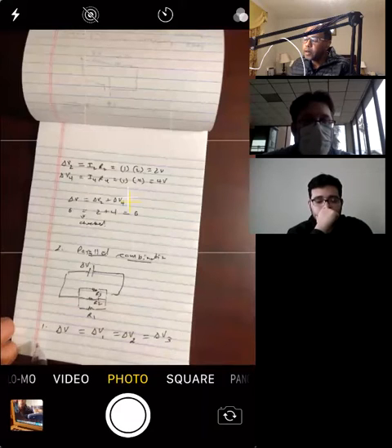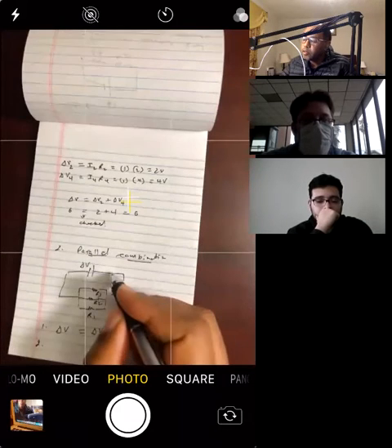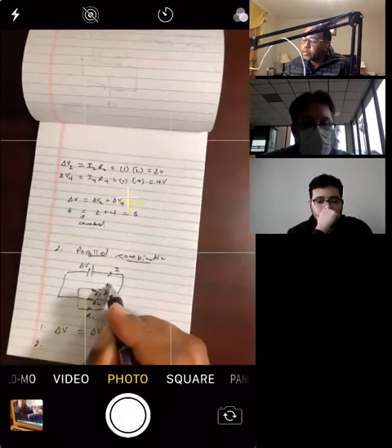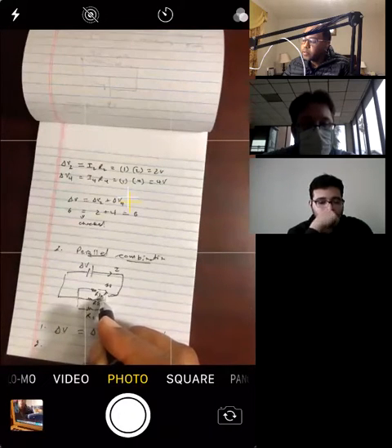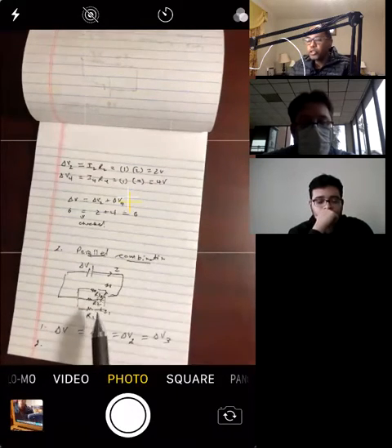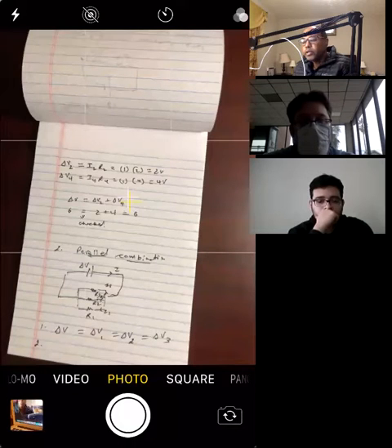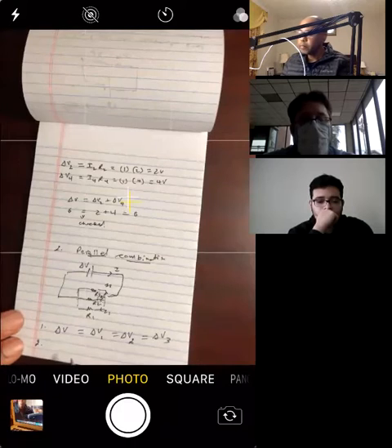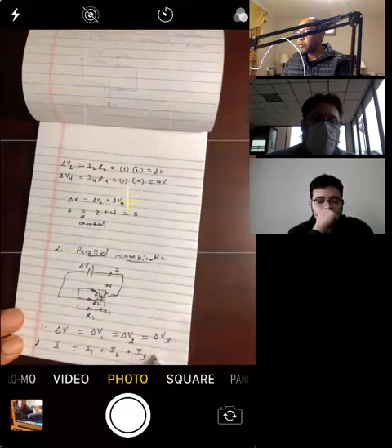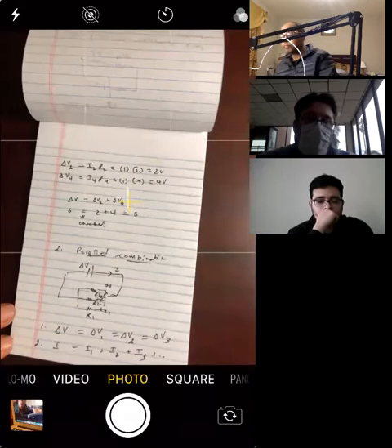How about the currents? Now you have this current over here. What's going to happen? Some of it will go this way, that's I3. Some of it will go this way, that's I2. And some of it will go this one, that's I1. So this current over here is branching into 3 currents, and the total current is the sum of all these currents. So the second property is that the total current is the sum of the currents across each resistor. If there are more, the same pattern continues.